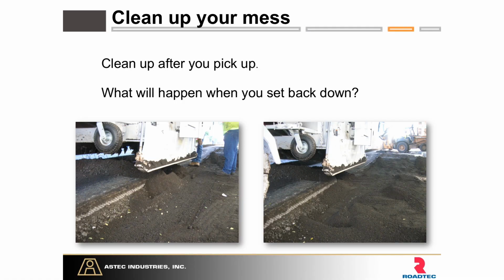At the end of each pass, we're going to have a lot of material built up in the cutter housing. It's just a little bit inevitable, but it's on the broom operators and the ground crew to make sure that the in-gates don't travel through this material. Sometimes we think we can add down pressure to these in-gates and it will just plow through, but that is very poor practice. We should just make sure that this is clean. Make sure that the pathway of our sensors is always the surface that we want it to be.